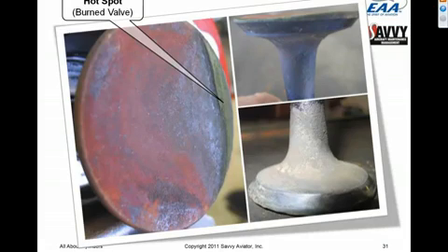Had this valve remained in service another 10 hours, that feather edge would have broken off. The compression in that cylinder would have gone to zero. It would have basically just shut down in flight, and the engine would have run extremely rough because it would be running on 5 cylinders, and the pilot would have probably declared an emergency and put the airplane down someplace. At any rate, again, symmetry is the key. Asymmetry means the valve is sick.